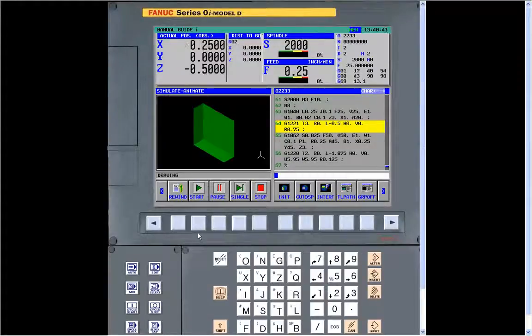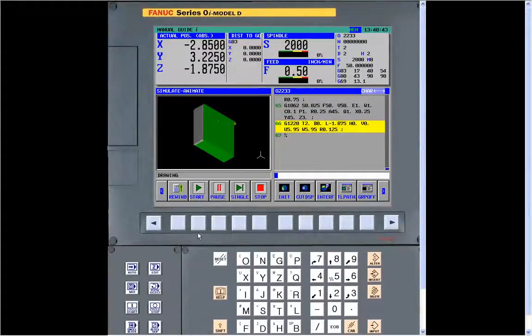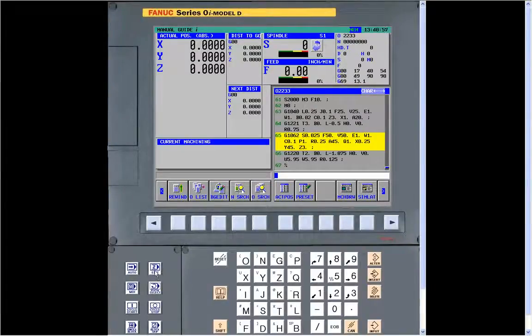And see now it's doing the pocket in the middle. And it'll show the tool going all the way around the outside. And see how it shows these green lines here? That's showing to where it's just barely cleaning up. So at that point, when we're getting our alarm at the end, we go group off, we go to edit.